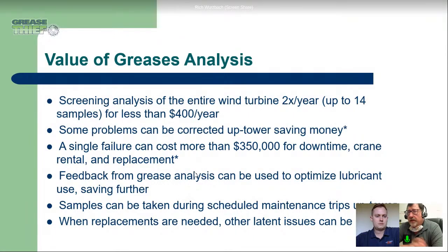Yeah, and you and I have talked about, for instance, a hot oil flush that someone might want to do. The question becomes, when do I do it? When is it time to do that? If we can monitor the condition of the grease, we might be able to create numerical criteria for that, right? Right. And oftentimes, through grease analysis, you're going to get an early indication of whether or not you're going to need to perform something like a hot oil flush.